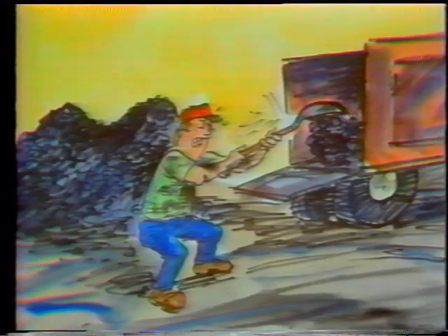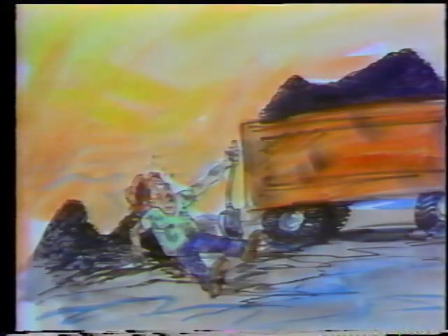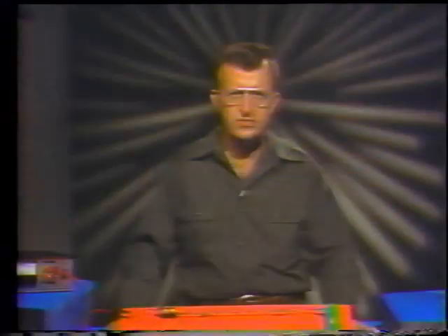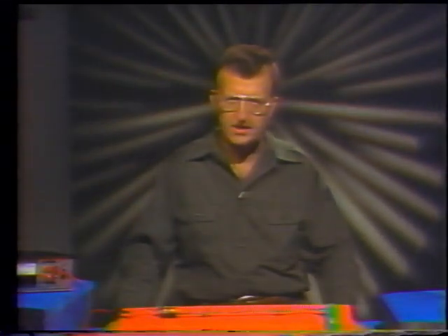It's important not to overload a generator. In that sense, they're just like people. If you ask them to do more than they're able to do, they'll overwork and break down. Loads are added onto a generator in 2 ways, in parallel and in series. Parallel loads are the most common. Parallel circuits are used to wire almost everything in homes and industries today. But you have series loads in the plant too. The DC motor starters, for example, are in series with their motors.